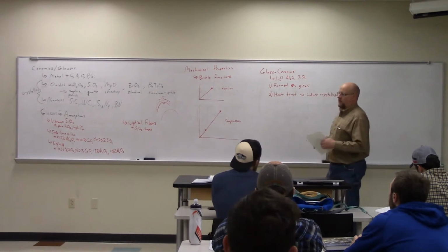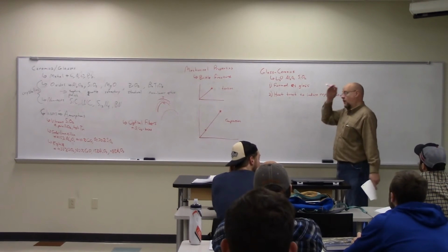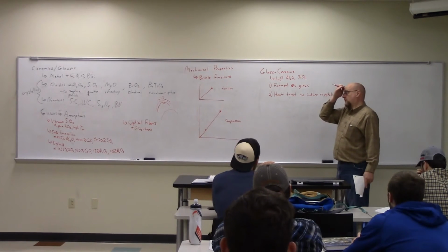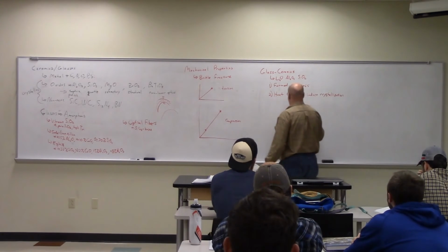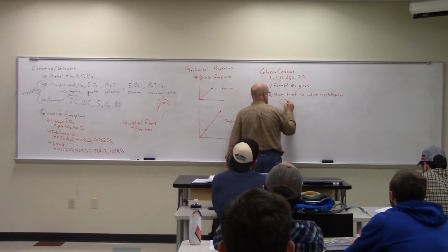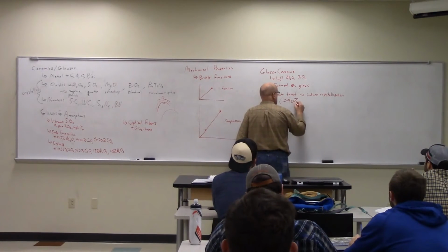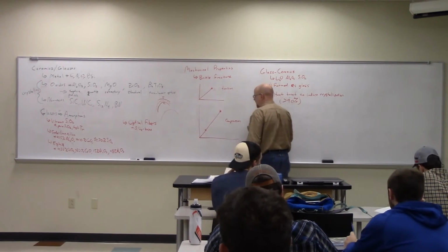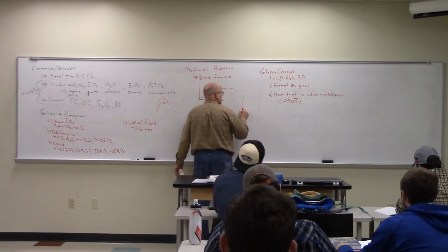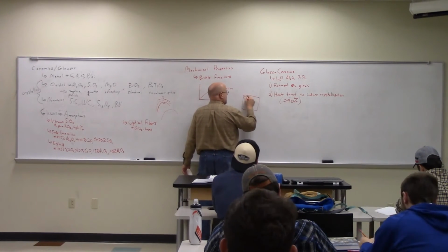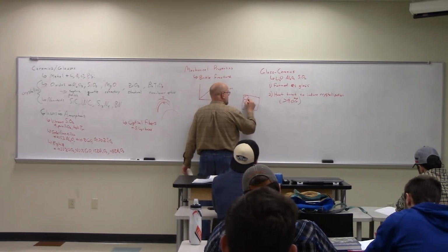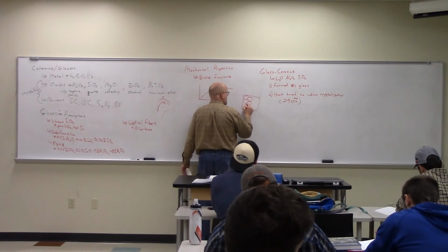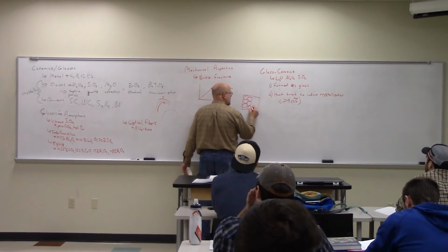So the crystalline material is actually harder than the softer glass. And typically you get more than 90% crystallization. So what you end up with in the microstructure is crystals with this gooey, glassy area in between them.